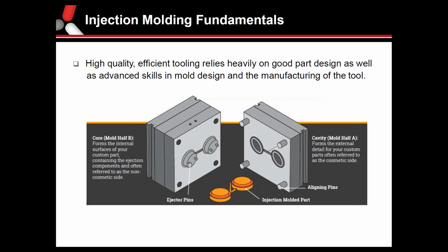Yeah, and for those not 100% familiar with injection molding, with the process, you have two halves of the tool. Your core, which is often referred to as your B half, and then your cavity or your show side, referred to as the A half. So when those come together, plastic shoots in via sprue, runner, gate. The cavities fill with plastic, and the mold opens, and parts fall out. So we've got an illustration in the middle of the page there, explaining that if you're not